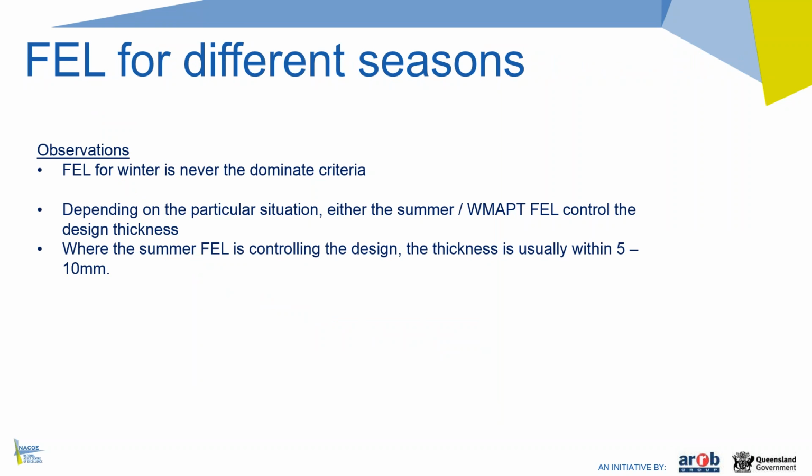Just on this fatigue endurance limit in the APA method, I think it would be beneficial to point out that the method proposes checking whether the strain is within the FEL for 3 different scenarios. First is the summer condition, the second is at the WMAPT, as Austroads usually considers at this temperature, and the winter condition as well. But based on our studies, some observations are that the winter FEL is never the dominating factor in determining the asphalt thickness.